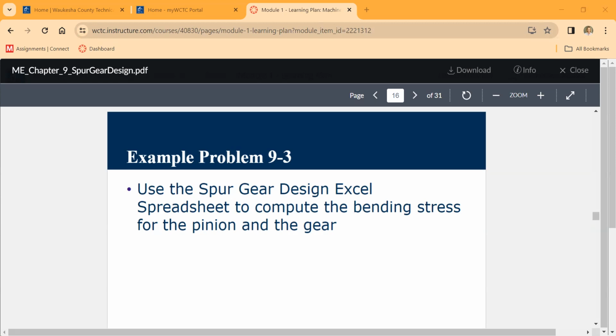And the desired output speed. Like I said earlier, many times you're going to have an output speed before you know the number of teeth on anything, but in here they're giving it to us in a different order. So I did the calculation, and our output speed is going to be 500. Then my spreadsheet is going to give you a suggestion, like, notice that the computed number of teeth here is 70. You would go to a catalog and see whether there is a 70 tooth gear that you can use. We're going to assume we can, because we're going to continue with this example. Your chosen number of teeth is, in this case, 70. That's the number of teeth on the gear.